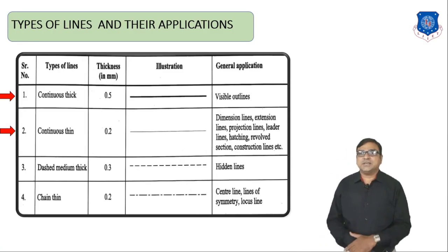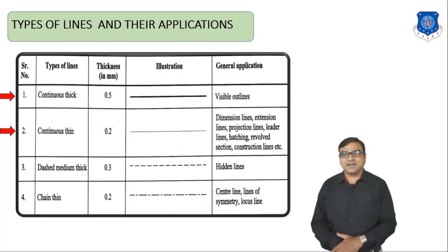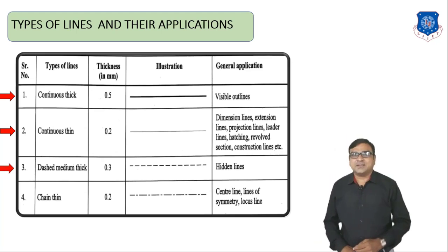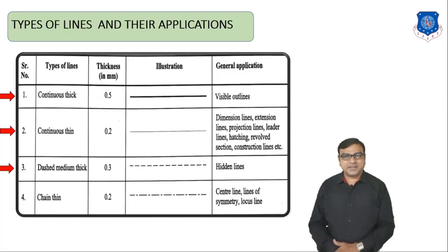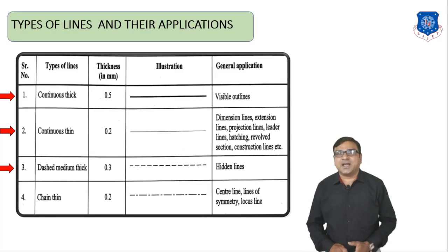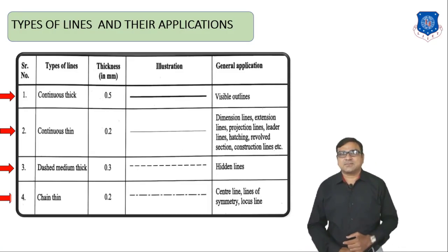It is used in dimension lines, extension lines, projection lines, leader lines, hatching lines, revolved section, construction lines, etc. Then dashed medium thick. It may be 0.3 millimeter and the illustration of that line is dash, dash, dash, dash. It is used to represent the hidden line of the surface or line.